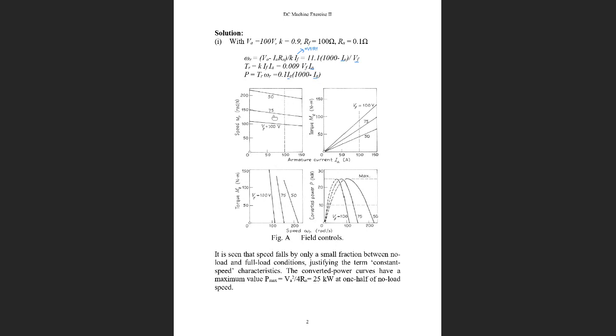So in comparison with the previous figures for the speed, a lower field voltage gives a higher speed, but the lower field voltage gives a smaller motor torque. Smaller torques. So if you would like the motor to be stronger, powerful, with big torques, you have to choose a relatively bigger field voltage. So bigger field voltage gives more torque output, but the motor speed goes down.